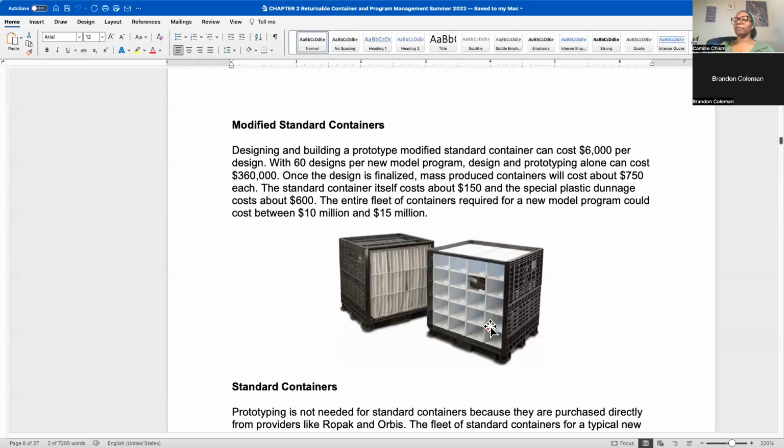So now the operator can reach these two levels. And then when these are empty, the operator can use that lift table to lift it even higher up. So instead of reaching down to this lower level, they can raise this whole container on the lift table so that this bottom row is now at their arm or shoulder or waist level, so they can reach it. So the idea would be that between here and here is going to be between your shoulder and your waist for reach. So the arm goes straight out and you're not reaching up or down, or you're not bending.